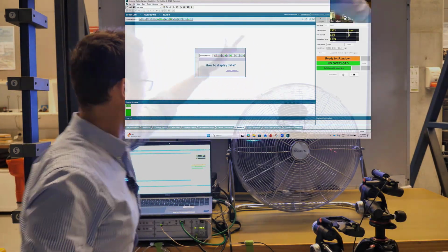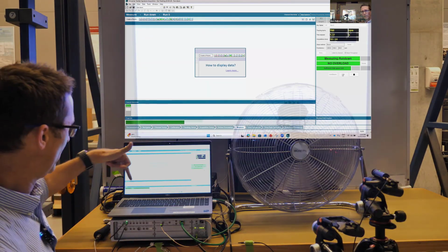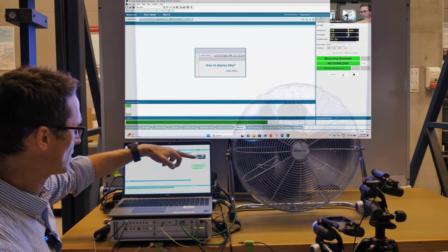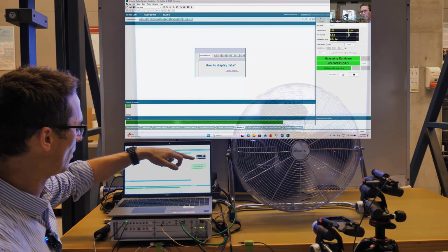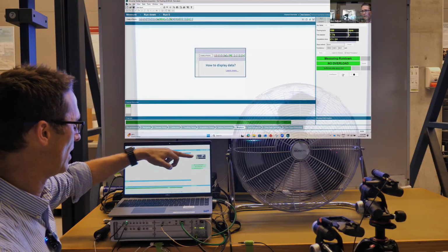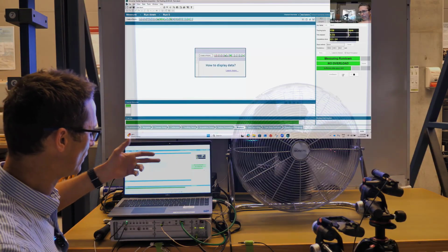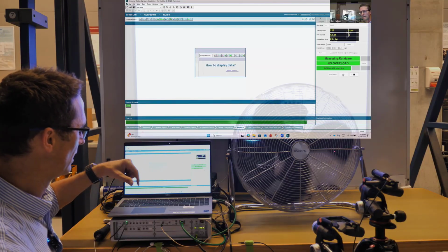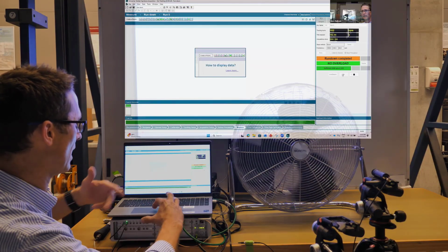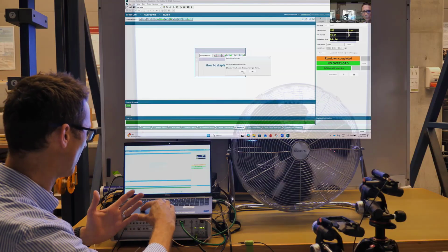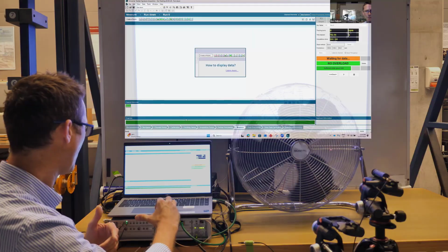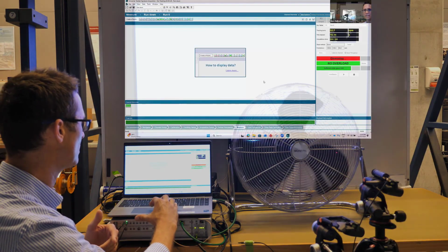on the fan, you'll see that at some point it drops through 1250, and you can see here the tracking RPM is progressively running down from that 1300 RPM to about 150 now, and there's one average left to do in a moment. We'll get the 150 RPM measurement, then the 100 RPM measurement is coming now. The rundown is complete. Would you like to save these data? Yes, we'll save those data. Disarm the system.